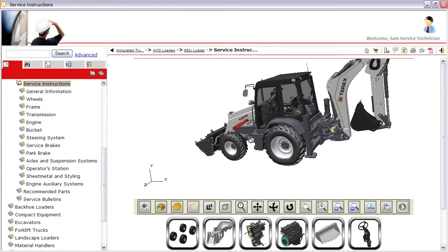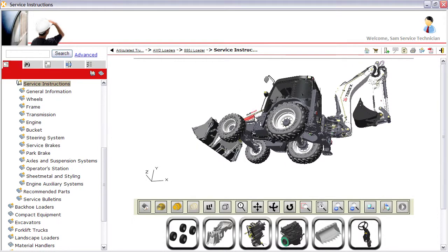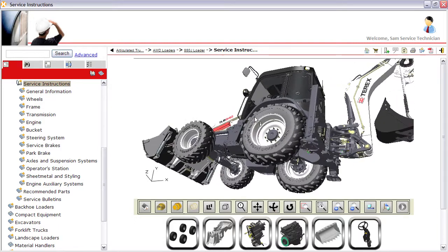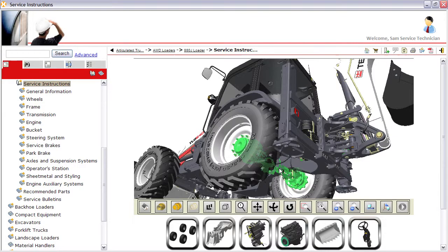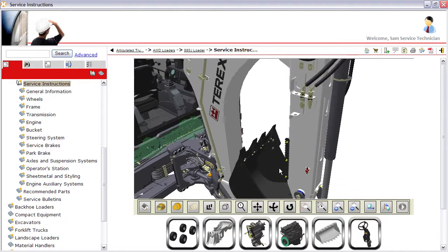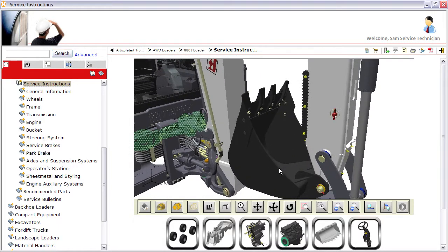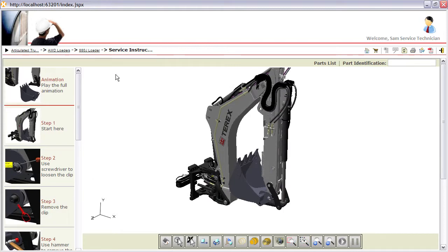Using 3D navigation, you can locate the exact part or subsystem to work on, eliminating wasted time hunting for service information and the potential mistaken use of unrelated materials for each service task. Once you reach the target part, you're presented with just the relevant information for this specific component, without any unnecessary or distracting data. This disassembly routine that I've just authored in Creo Illustrate is a series of interactive graphics.